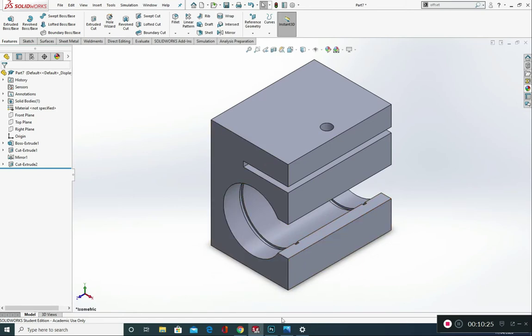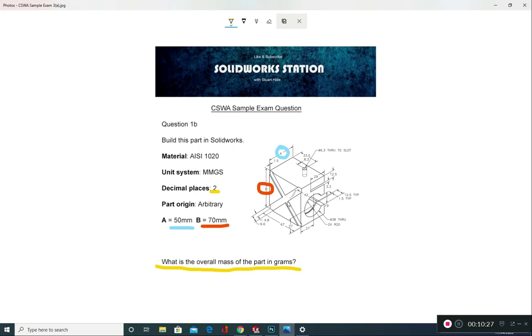Okay, for our next step, let's have a look at our drawing. We're going to put in this large cross shape that we've got here. It's saying that the gap here is 9.6. Midway is 4.8. So what I'm going to probably do with that is draw two center lines down here in an X pattern. Then probably use the offset entities button to offset bidirectionally by 4.8. Then from there I'll produce a cut extrude which will be 1.5.